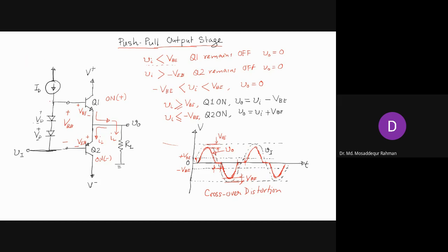If you look at the diode characteristics, the diode characteristic is something like this. You have voltage VD and the diode current ID. With the increase in the voltage, the diode current initially remains very close to zero. After a certain voltage, it starts shooting up, increasing exponentially. This voltage where the current starts picking up, do you know what it is called? Do you remember? It is called the cut-in voltage.